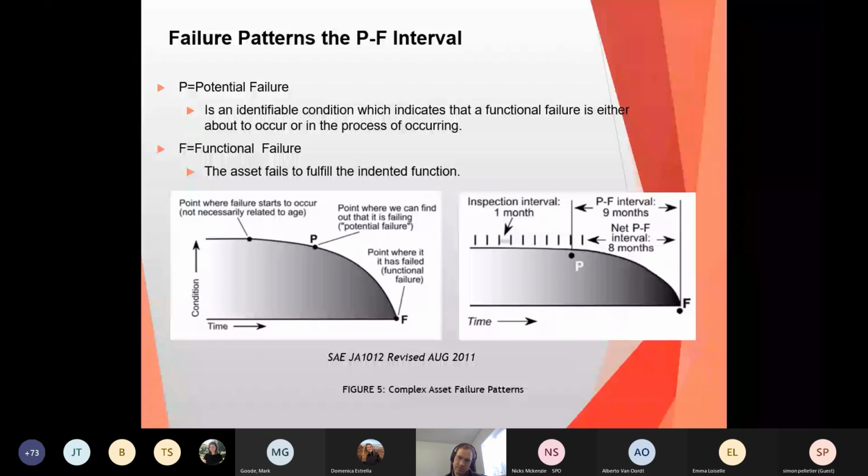Now that rule applies the vast majority of the time, but if multiple failures start to occur, such as significant misalignment occurs and no other maintenance tests are being done, such as stroboscopic or temperature monitoring by the site or by autonomous systems, failures can develop in shorter time periods than that.